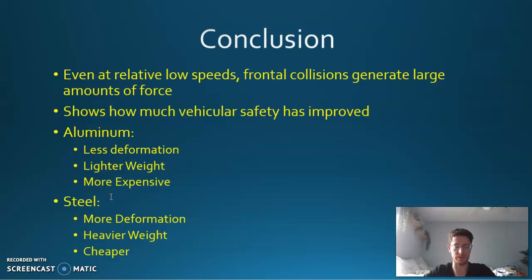However, depending on the type of application, steel might make more sense, mainly because of the price advantage, for which I wasn't able to get a specific number, but from what I saw, it's usually between 20 to 30% cheaper to make a steel part than aluminum. One thing though that probably would impact the overall weight is that, from what I've seen, the steel models for those impact bars are usually stamped steel, so they are simpler shapes than what I used, and usually thinner, so that weight difference wouldn't be as significant.